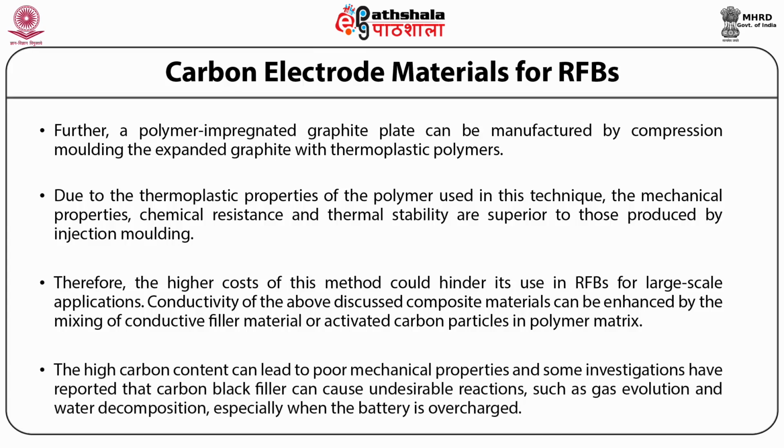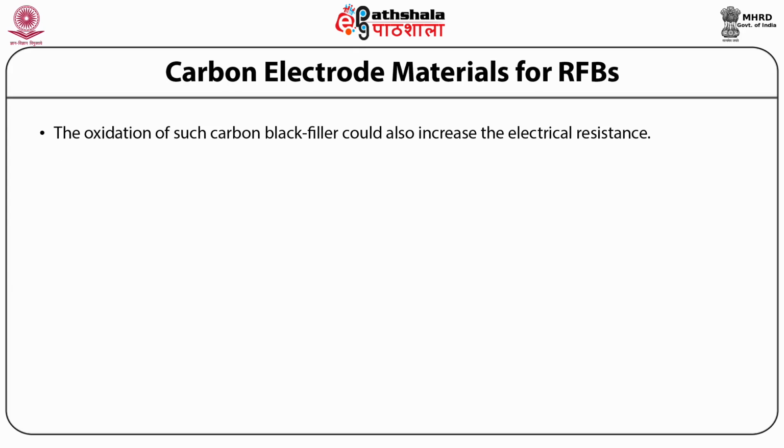The high carbon content can lead to poor mechanical properties, and some investigations have reported that carbon black filler can cause undesirable reactions such as gas evolution and water decomposition, especially when the battery is overcharged. The oxidation of such carbon black filler could also increase the electrical resistance.